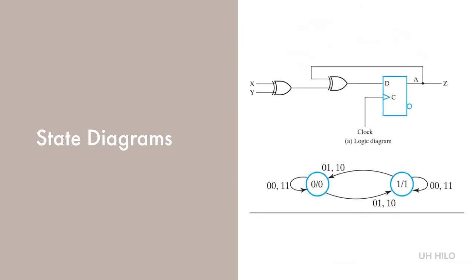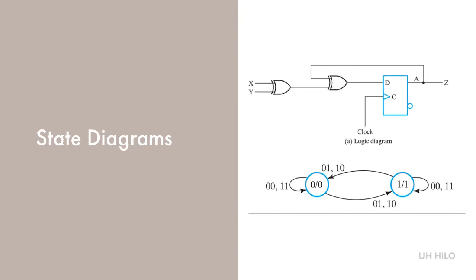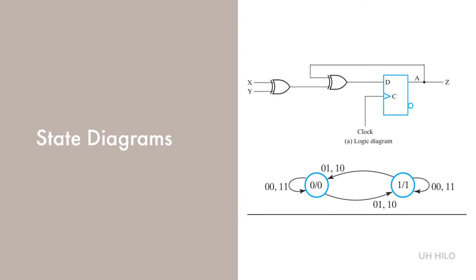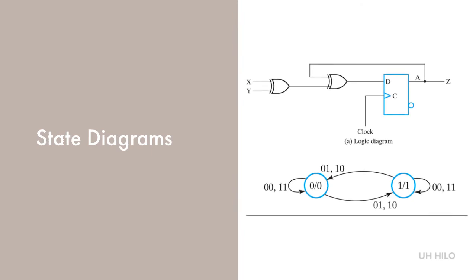Consider a logic diagram for this circuit. Here only one flip-flop with two states is needed. Here we have a Moore model circuit. The slash on the directed lines is not included since the outputs depend only on the state and not on the input values. The output is indicated inside the state circle, separated with a slash. There are two input conditions for each state transition in the diagram, separated by a comma. When there are two input variables, each state may end up having up to 4 directed lines coming out of the circle.